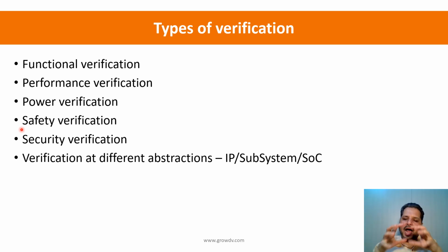There could be an IO subsystem which connects all your peripheral type of devices. You could have UART, SPIs, PCI, USB type of a group of systems, and then you have your memory controllers that could become a memory subsystem. Then you have multiple CPU cores that could become a CPU subsystem. So all these subsystems are created separately. So you initially verify each block of them and then put some of these together, and then let's say I verify IO subsystem, memory subsystem separately, CPU subsystem separately.